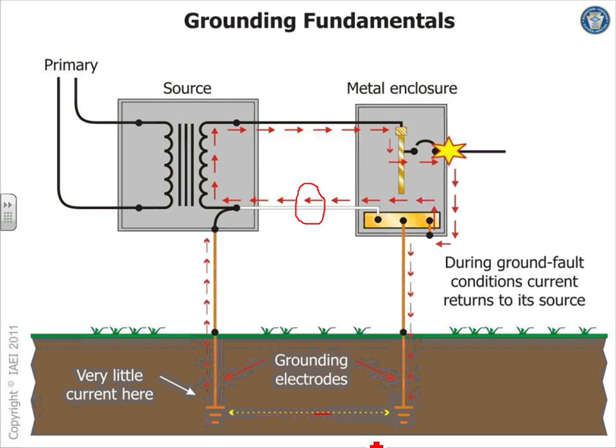I like this one because of what happens if you lose the neutral, especially if you have a storm, on a single phase three-wire system. If you lose a neutral on a 240/120 split-phase system, or 208/120, or 480/277, that minor connection here could at least stabilize the voltage for you. It will stabilize the neutral enough not to burn the building.